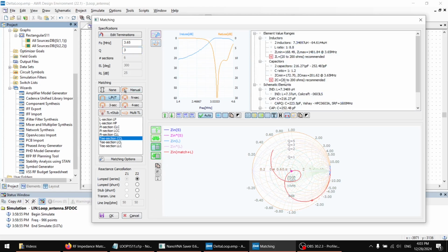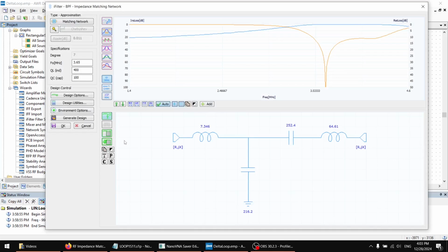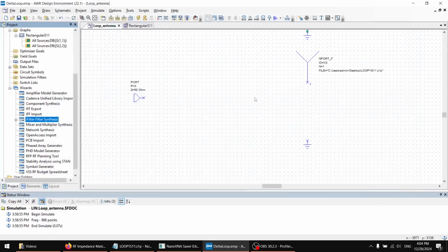And you can also look at the lists. Here we've got the warning because we are dealing with really high impedance in this case, right? This is like a few kilo ohms or something. So let's go further. Again, you can look with different spans and so on at this network. So this is actually quite handy. I wouldn't expect the circuit to be this wide with real Q of such high inductors, because this will have some resistance. You can actually change and play with this here, but I will just skip it and go further.